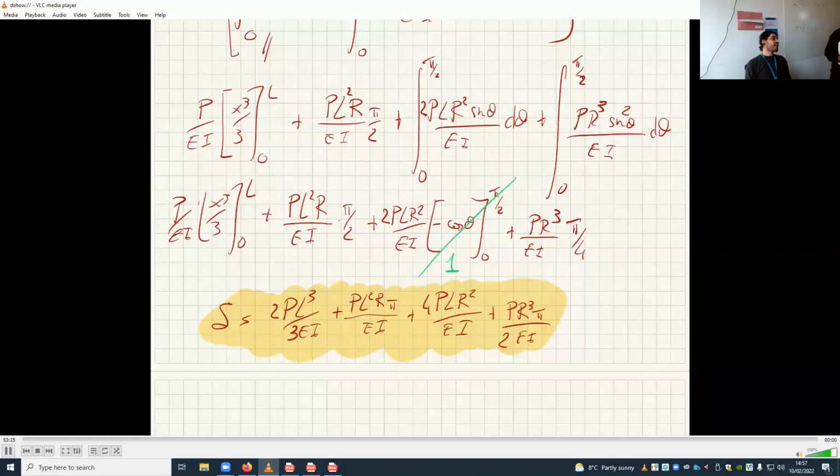Yeah. You can find the diametral interference, which is U1 minus U2, so how much is the radial displacement of the inner fiber of the wheel, and how much is the radial displacement of the outer fiber of the shaft, and then you can find the radial interference, and that's a function of P_c. So you can find the largest P_c that you can get, the smallest P_c that you can get, and that gives you the largest interference or the smallest interference.